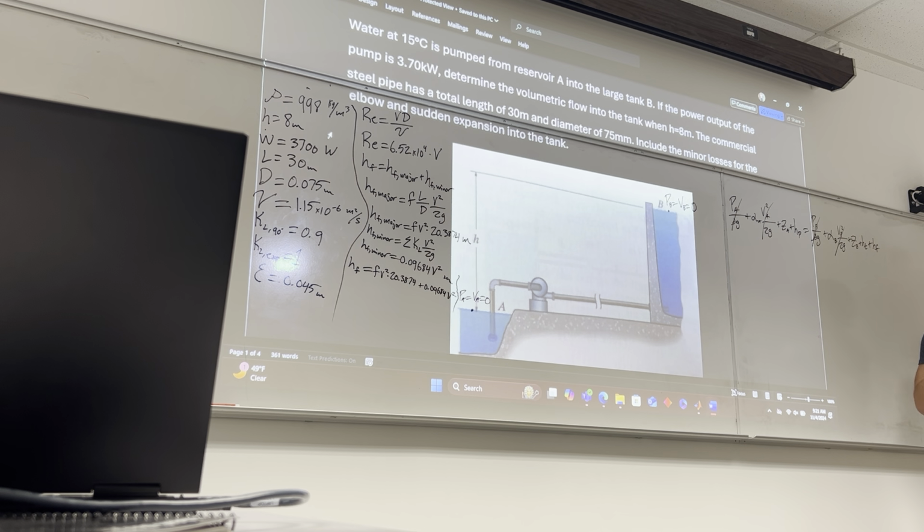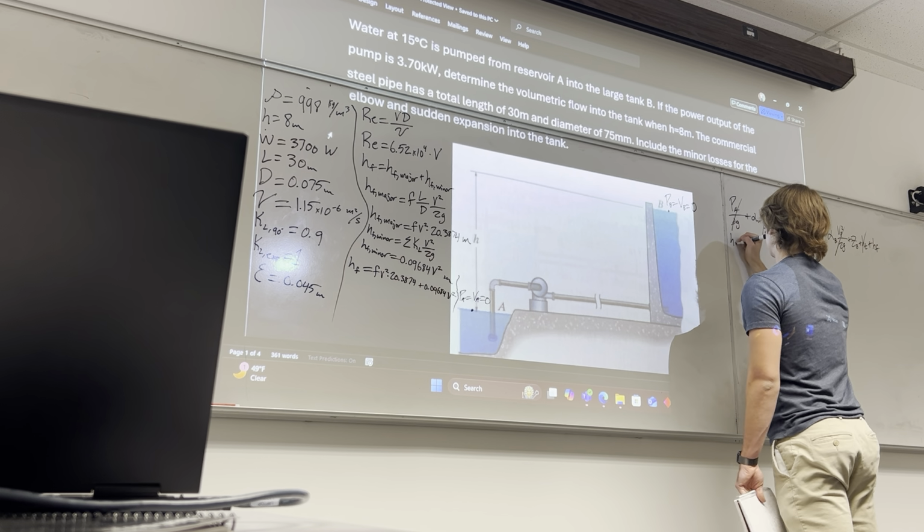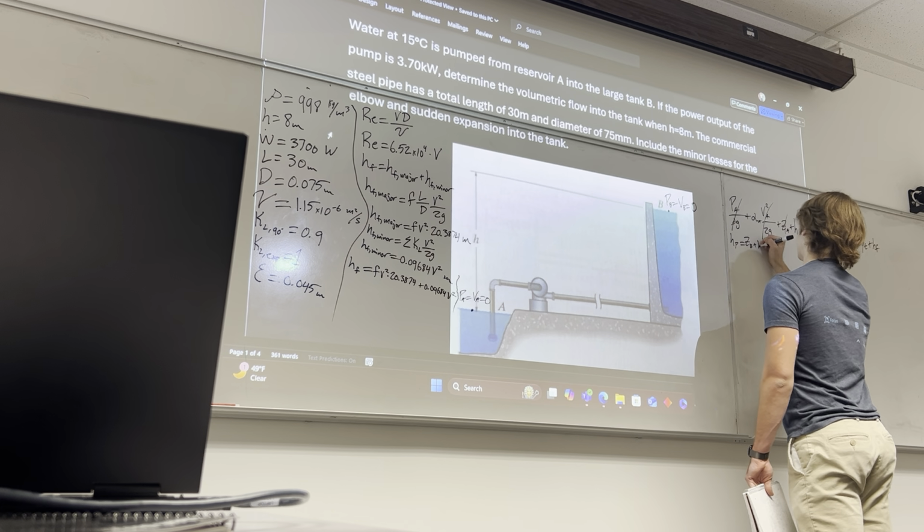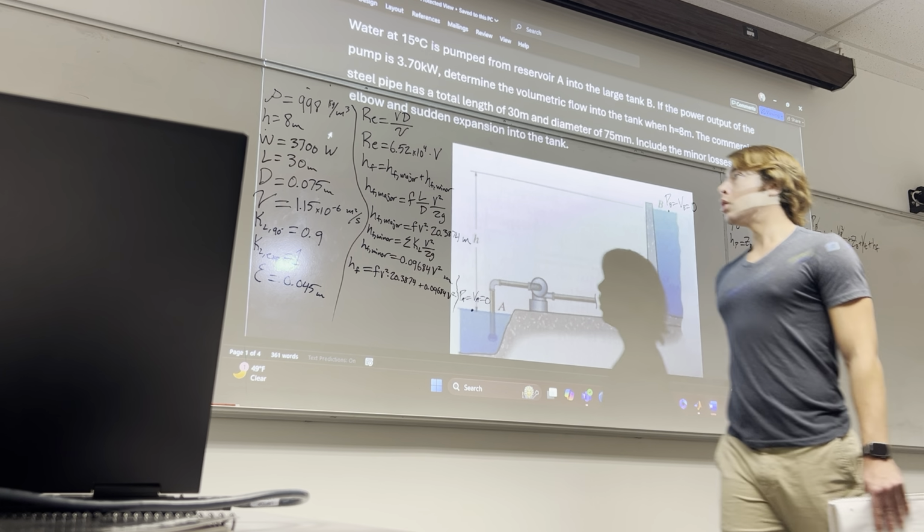So not very difficult math there, but you can see I'm not even talking about it much because velocities in this problem don't matter at 0. You would also call ZA 0, and there's no turbine. So we get HP equals ZB plus HF, right? And so